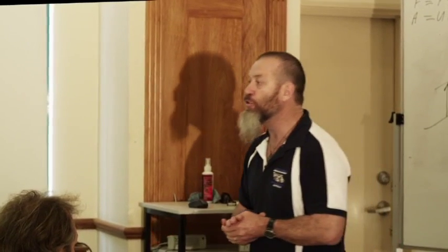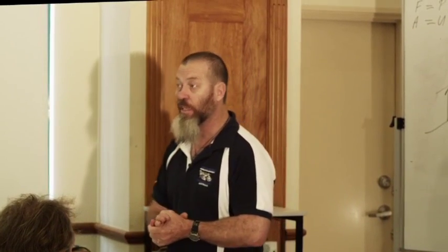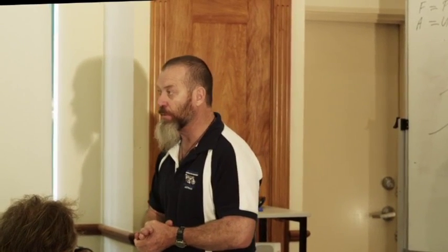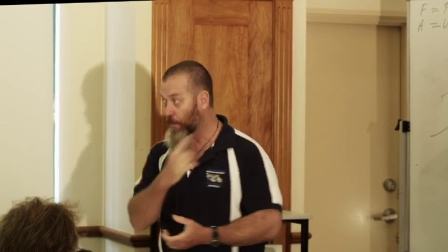Okay? I'd like to ask you to consider doing this in future. Don't use Dynabolts or nails on your external wall frames. It's only going to be a problem when the building blows away. And I've got pictures. I'm going to show you pictures at the end of the day of when a building blows away. Old mate in Cairns would have seen it 1,000 times. That's the only time it's going to be a problem. Now, one other thing,